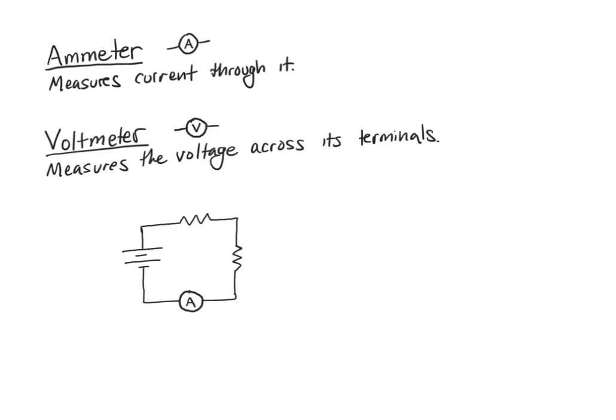It's a little bit more complicated again with the voltmeter. So for example, if I bring it back to where I had it before, we have several things to think about. One is, in order for it to still be true that the current through the rest of the circuit is unaffected, it means we shouldn't have any current through here, because if we did, the current through the battery would split.